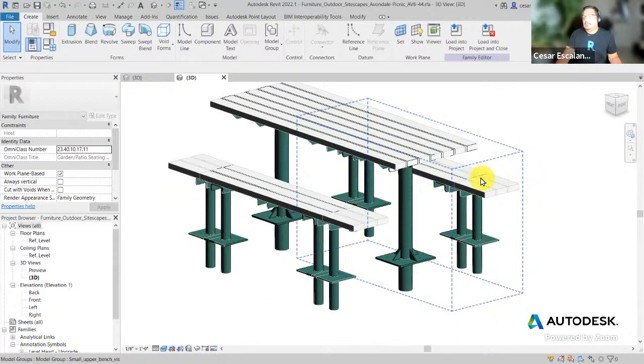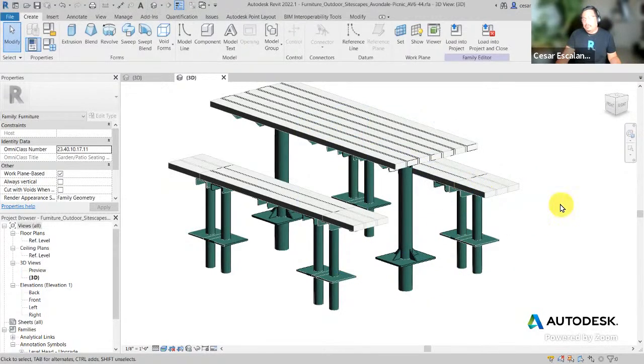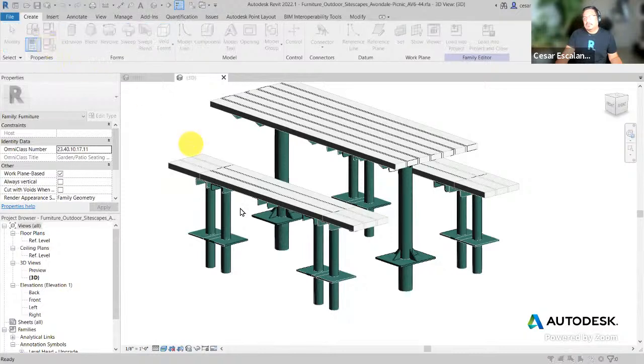This is the family editor, and we haven't talked about the family editor yet. But when you open a family with the extension RFA, you're going to open the family editor. One of the buttons that the family editor has is something called Family Types, which is a dialog box that discloses all the internal information inside Revit. It's here.